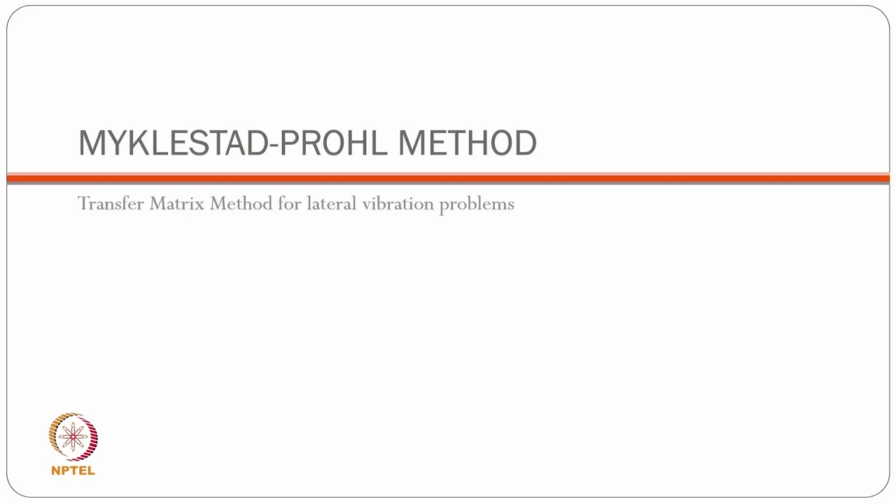That is how F and X will replace T and theta in the Holzer method to generate the same formulation for the longitudinal vibration problem. So, longitudinal vibrations of a propeller shaft or that of the push rod, all of that can be analyzed conveniently using the same approach which we have discussed as the Holzer method.